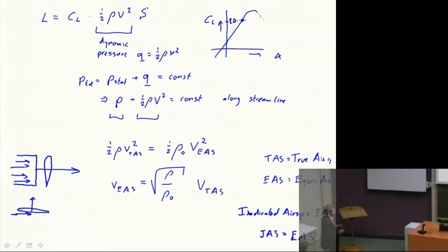So it's a very minimal angle of attack. Well, 10 degrees is still a lot for aerodynamics. But just to give an idea of the magnitude of the force, it would be the same as if you would stop the flow, so you would need a shape more like this, I guess. The force that you would feel as a drag if you use a sort of container that has a similar surface in the back as the surface of the wing. So that's what I meant when I said if you put the wing perpendicular in the flow, then the horizontal force you would feel has the same order of magnitude as the lift force that you feel when you have a CL of 1. Just to indicate the huge force that you feel when you only have a fraction, like 5% or something like that, of the drag. Remember CD over CL ratios that were discussed last time. So something like 0.05 is then the drag coefficient when you have a CL of 1.